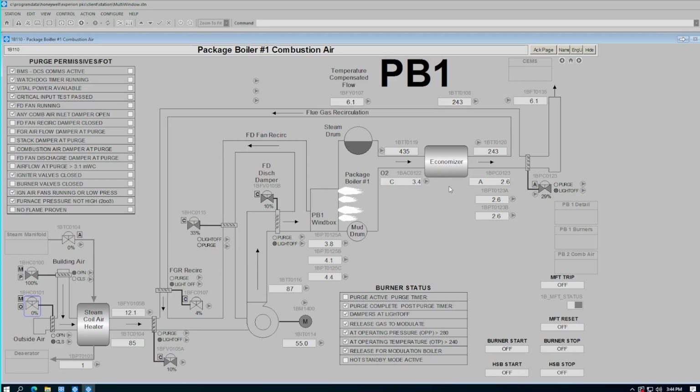After the burners, the flue gas goes through the economizer. The hot flue gas is used to preheat the boiler water. Then it goes up the stack through the CEMS, which stands for Continuous Emissions Monitoring System. Some of the flue gas gets recirculated for unburnt fuel and its heat. We have another recirc line here, and this is for light off.